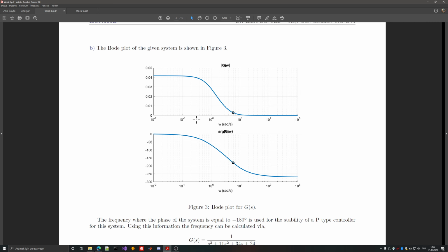Since k g divided by 1 plus k g is the closed loop, we can easily see that 1 plus k g should be equal to 0. Now, this implies that k times g is equal to minus 1. Therefore, in the frequency methods, this minus 1 is most of the time very important for us, because we look for certain parts of this minus 1.